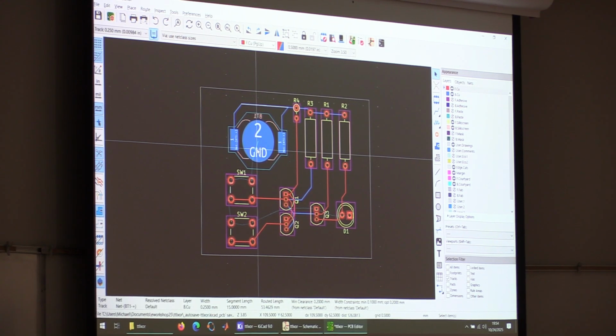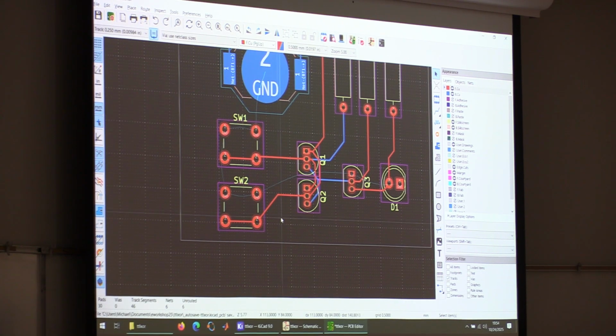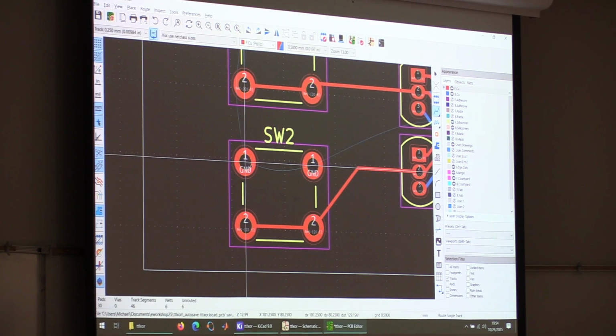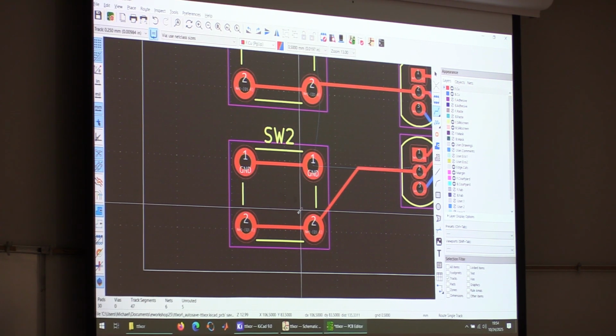They'll disappear when your design is at its final stage, kind of complete. Those just indicate connections, so you can't really select them. If it isn't connecting for certain components, do you have a trace going to each one? Because typically, this line here between these two pads should go away the moment I place a trace on it.